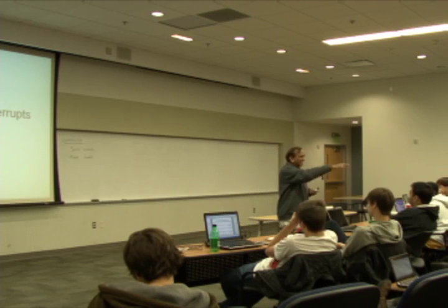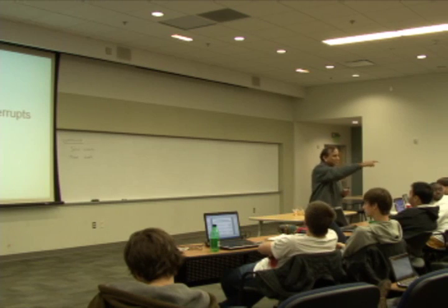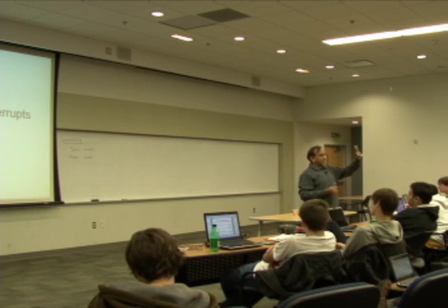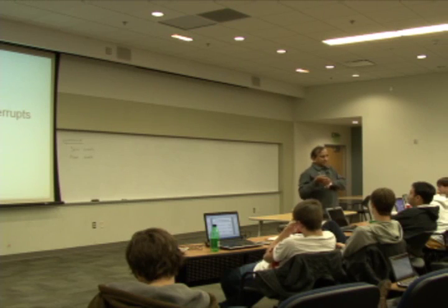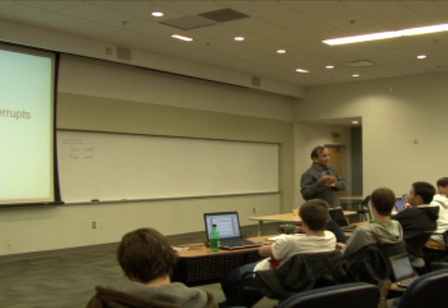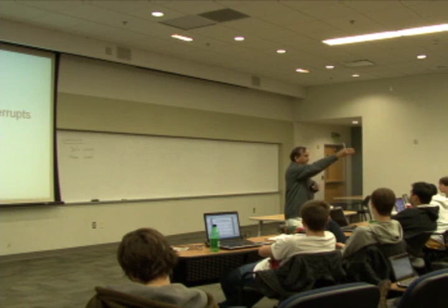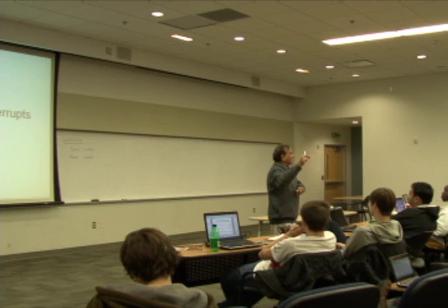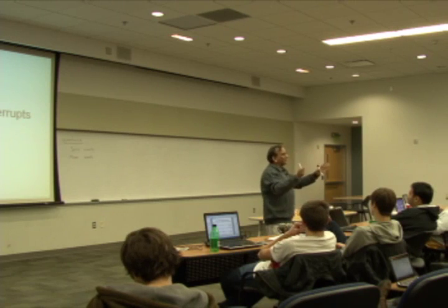I want to get your name. You're Tim, right? Okay, so what is your name? Jonathan, right. What is an example of an asynchronous discontinuity, of the three that we mentioned? Is an exception asynchronous? It's not, right? Similar to what Peter said, you know exactly where it is going to happen, because you know the data flow, and you know that if you have an operand that's 0 and you're going to divide by 0, when you hit that instruction, you are going to get that, right?